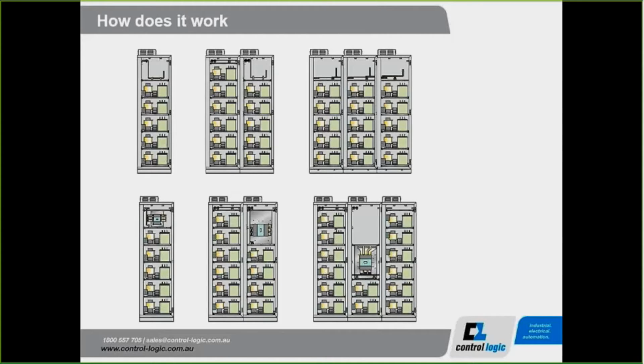The way it does that, it simply energizes a relay output or relay outputs on the controller. These in turn are wired to the coil of the contactors, and it energizes the appropriate contactors, thereby putting that particular tray or step into the circuit. So that's basically how the power factor controller works. So we're just moving forward.